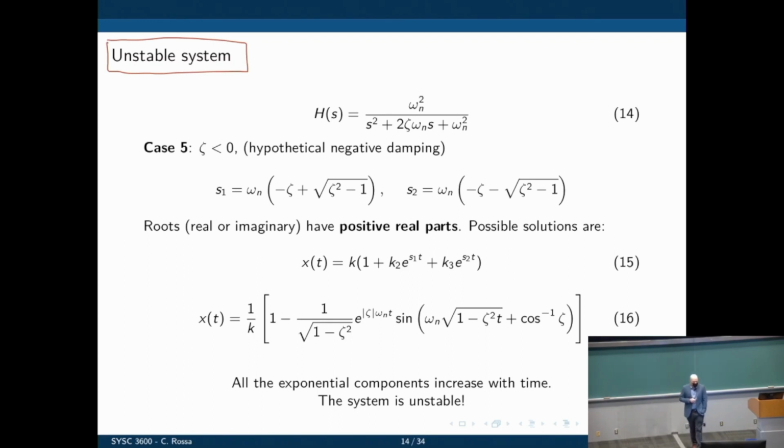And when we do that, we can see here that when the damping ratio is smaller than 0, the real part of our poles now becomes positive. We put a negative number for zeta there, and now the real part is positive.